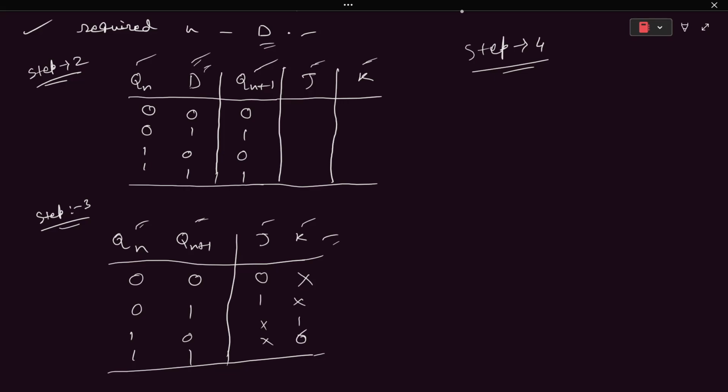In that case, the available flip-flop's Qn and Qn plus 1 inputs are there. The flip-flop that we must build has only a single expression here. Suppose we were told to build JK to SR flip-flop, or any other flip-flop which has two inputs, then we will have 8 possible combinations here, but in the excitation table, we have two possible combinations.